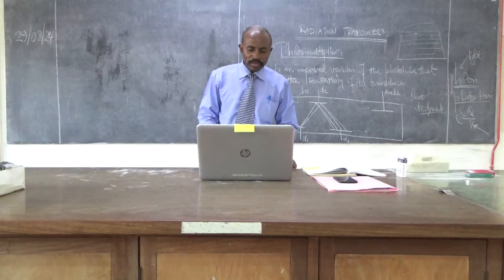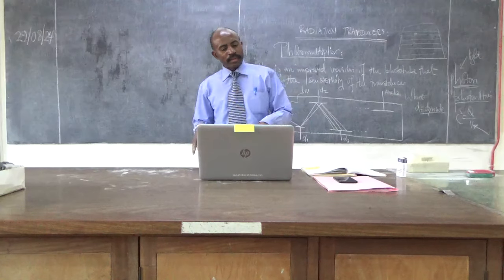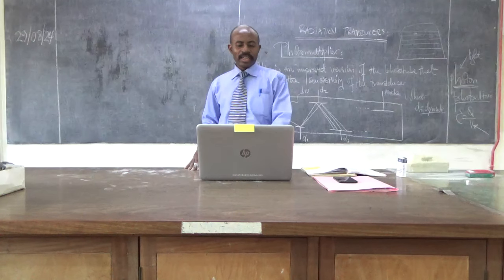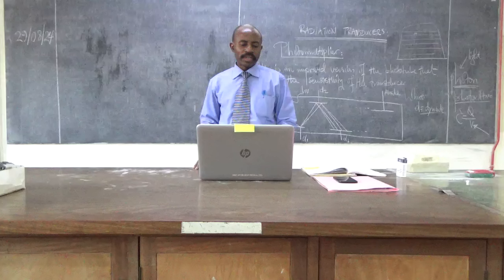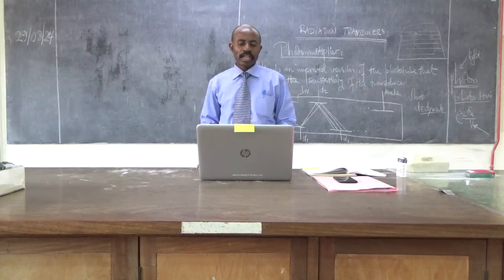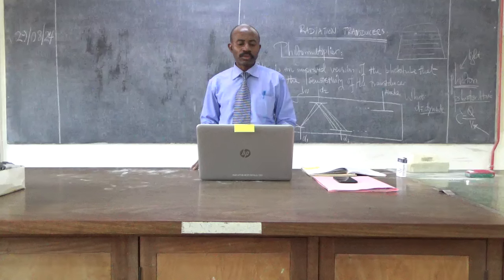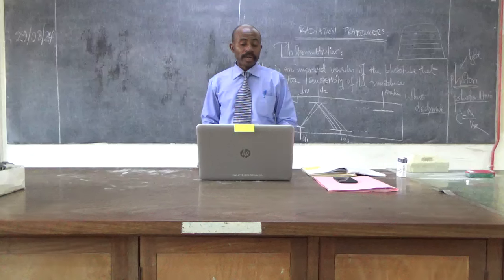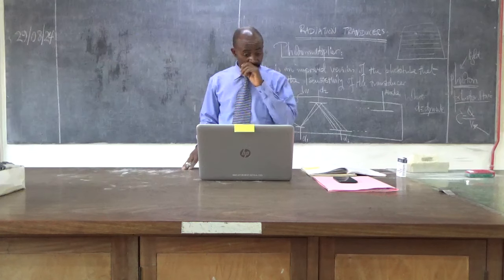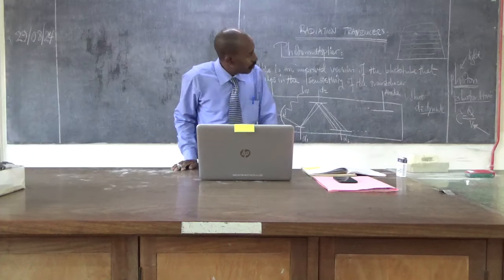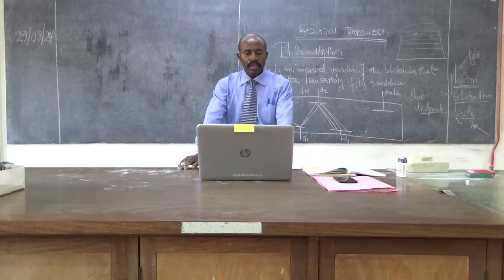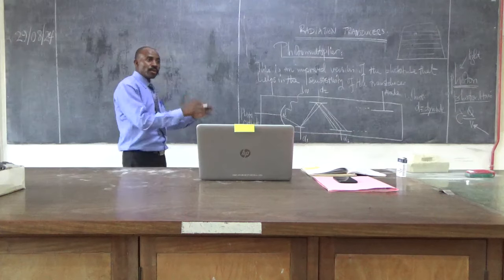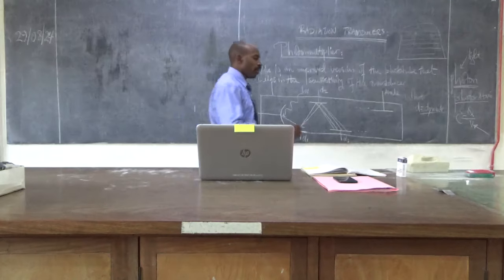The first electron striking the dynode causes another two of them to be released, the two release four, the four release eight, etc. Quite often, the physical placement of the dynodes and their shape are designed to control the gain within the photomultiplier tube. The supply voltages necessary to accomplish this vary from about 600 to 3,000 volts. The rest you read on your own. I'm just trying to scratch the surface.